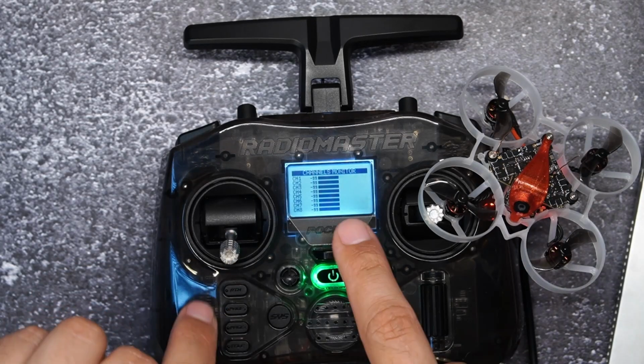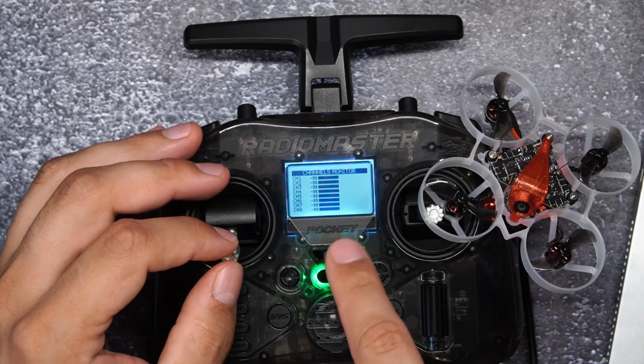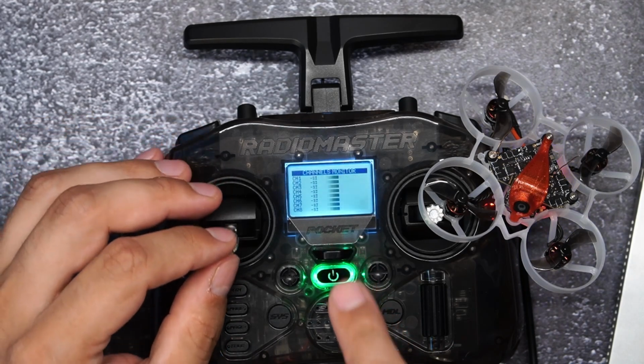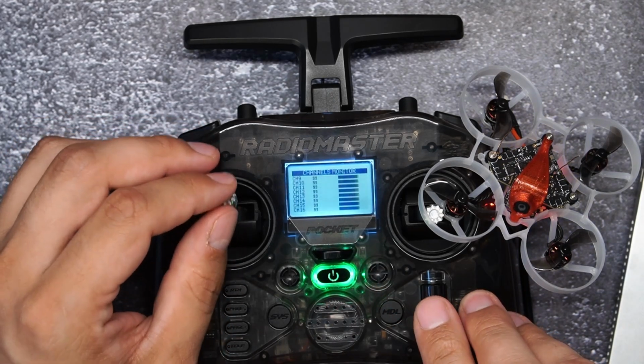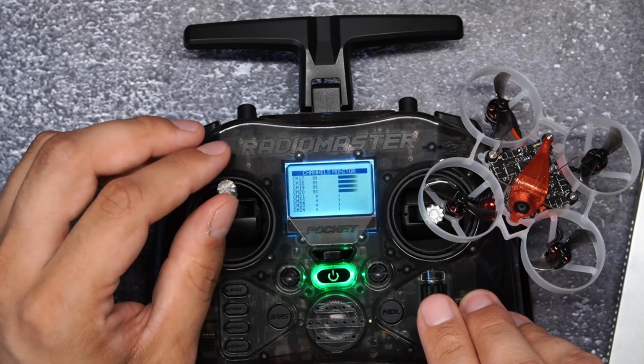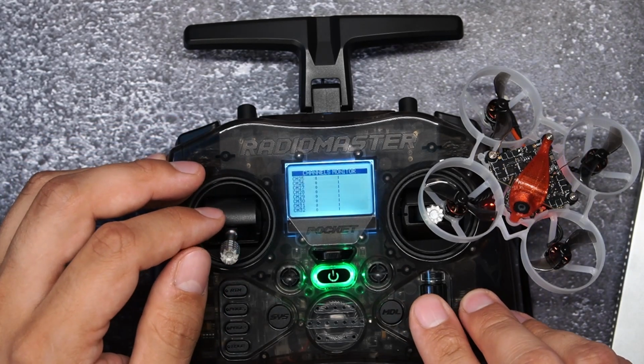So we've checked the packet rate, what it affects, and we've got some base knowledge about physics, and we came to the question of packet format. And answering the question, why do I need the packet format knowledge and what does it affect, let me show you one experiment. The experiment is as follows. I took all channels and configured them to transmit the value of the throttle stick. So all should transmit these accurate, slowly changing values.